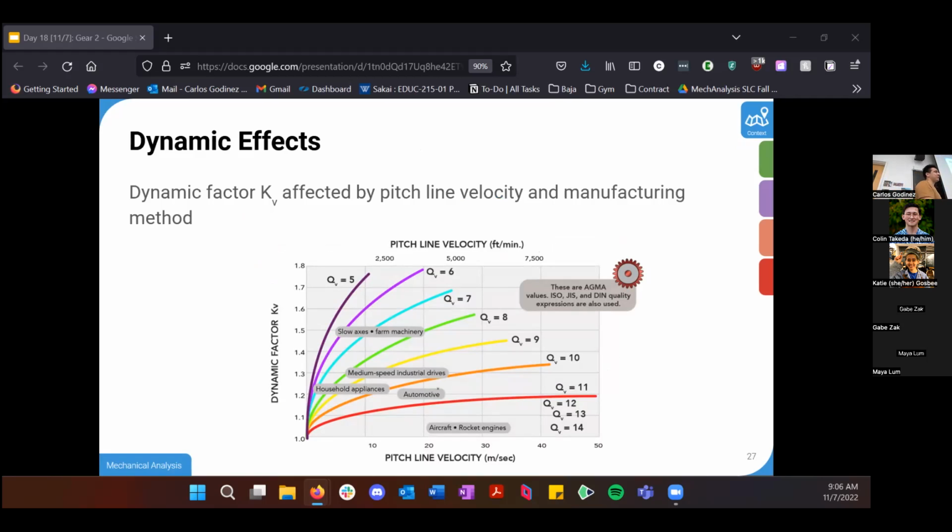What they did is that they took that first cantilever beam assumption, played it out a little bit, futzed with the geometry, and then they did hours and hours and days of experimental testing where they just had 2 gear trains going, churning at different speeds. The first order approximation got you in the right ballpark, but there was still a little bit more fudge factor that you needed to add to it. That's where the dynamic factor comes in, based on how fast your gears are spinning, because the faster you go, the more load you're going to have, obviously, from dynamic effects.